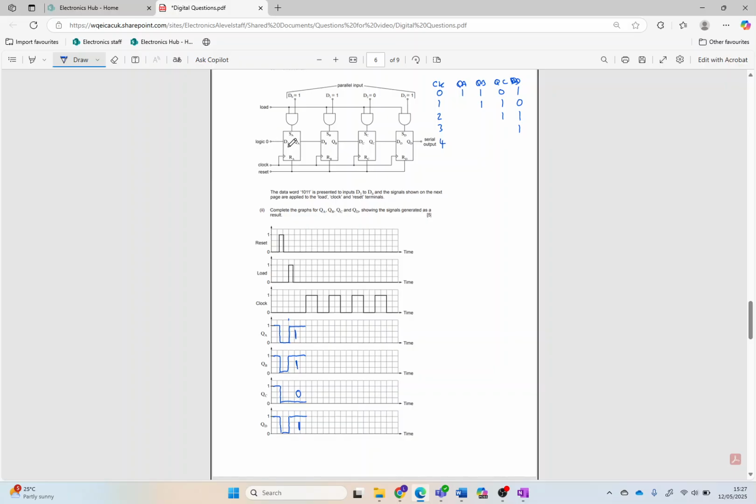After the first clock pulse, looking down, this is going to go to a 0, because the 0 is going to come in. So we're going to have zeros all the way down there to flush out our register. So effectively, we've only got that 1 there to start with. On that first clock pulse, that is going to go low, and it's then going to stay low.